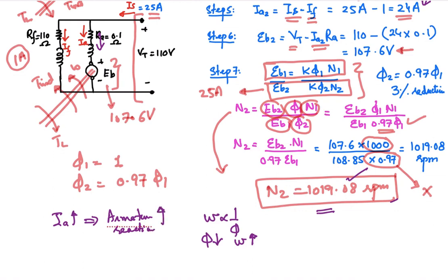We have discussed its effects in the theory class: because of the armature reaction there is a shift in the magnetic neutral axis and a decrease in the net flux of the machine. What are the possible remedies? Change the position of the carbon brushes, introduce interpoles, or use compensating winding to compensate for that change in the flux brought by the increase of the armature current.